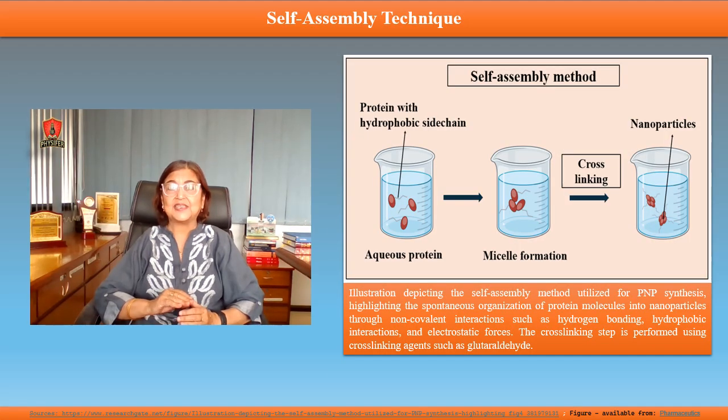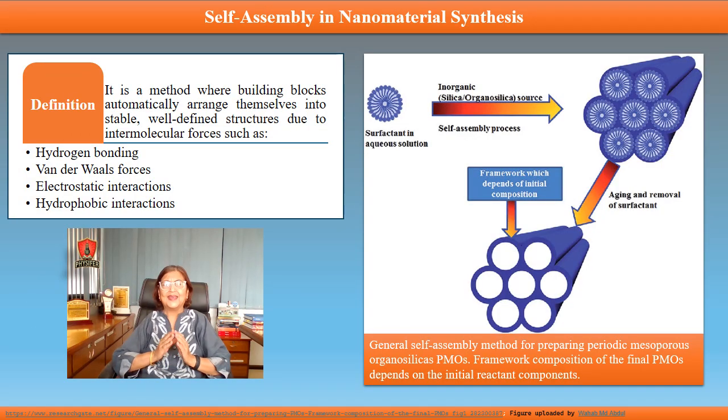Next is the self-assembly technique. This is the process in which atoms, molecules, or nanoparticles spontaneously organize into ordered nanostructures without external direction. In the self-assembly technique, building blocks automatically arrange themselves into stable, well-defined structures due to intermolecular forces such as hydrogen bonding, van der Waals forces, electrostatic interactions, or hydrophobic interactions.